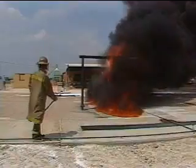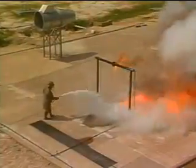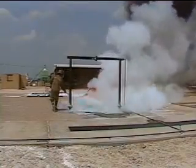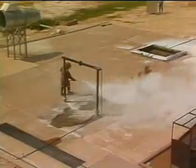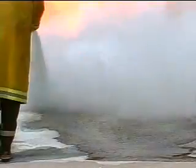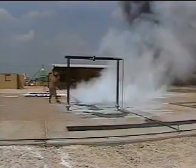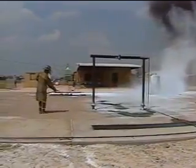Approach the fire from the upwind side of the fire. Direct the stream approximately 6 inches ahead of the flame edge, using a rapid side-to-side sweeping motion. Each sweep of the chemical stream must be slightly wider than the near edge of the fire. Advance slowly, working the fire to the back edge of the spill. Extinguish any remaining fire at the back edge of the spill by aiming directly at the flame. Do not stop your sweeping motion until the fire is extinguished.